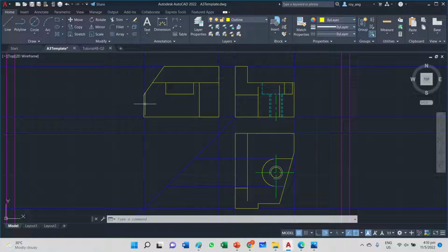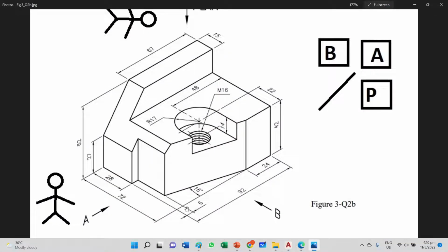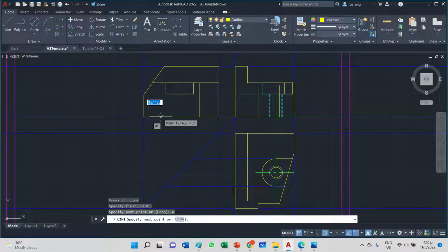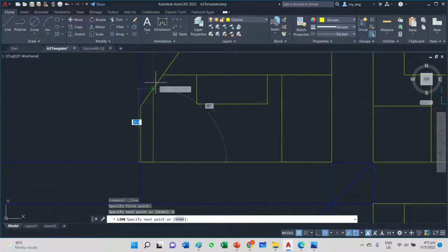And there is another segment over here that's shown. There is an offset of 6 millimeters. So I'll draw a line up this line over here. I know there's an offset of 6 millimeters, right? And it shares this line as well. So I'm going to draw that. I'll click on here, go by 6, and then I will go all the way up, and it will intersect this point. Remember to delete away the small little line segment that is shown here.